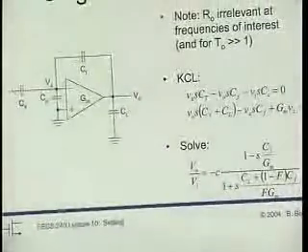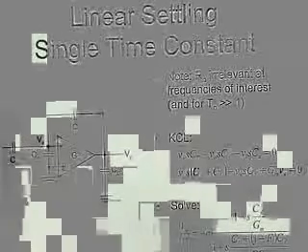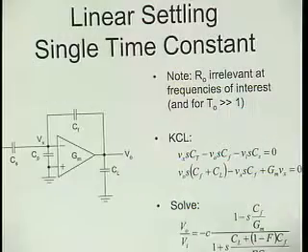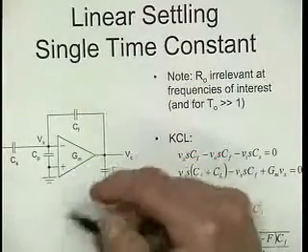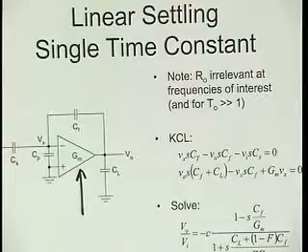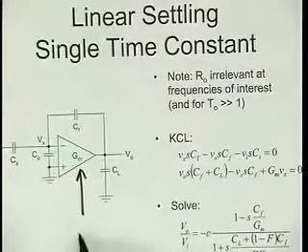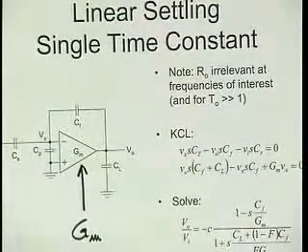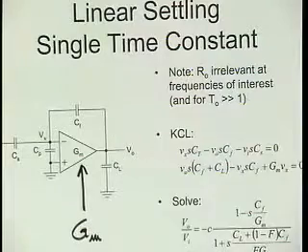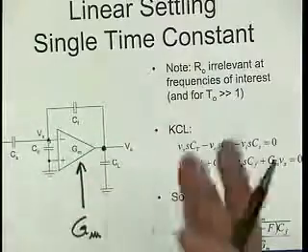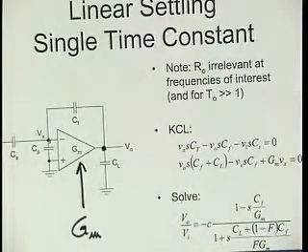All right, so first approach, again, simple. That's kind of EE40, right? A single time constant, linear circuit. Here, instead of having an amplifier with a fixed gain, which is a reasonable model if I'm willing to wait long enough, I replaced this with a transconductor. Combined with the load capacitance, the feedback loading, and so on, that gives me a finite bandwidth. It's one single time constant in this circuit, at this node here, because the only capacitor is just a divider, right?